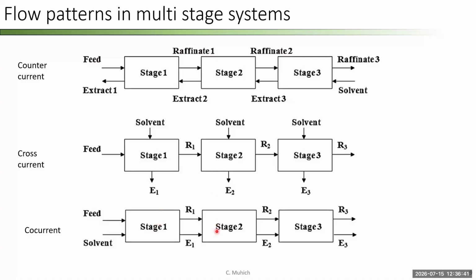I take both the raffinate, the stuff that is holding behind, and I have my extract. I move it to stage two. I reestablish equilibrium. I then move to stage three, and I reestablish equilibrium. This is a very ineffective method because as I move from stage one to stage two to stage three, equilibrium is going to be reestablished. And so these three stages are effectively the same as if I had moved directly to stage three.